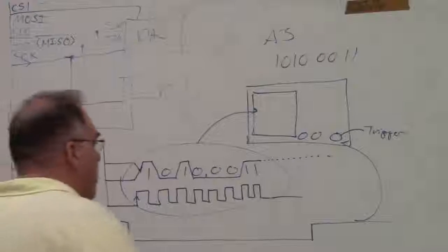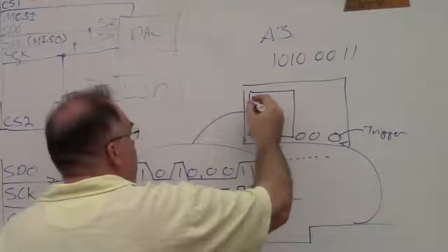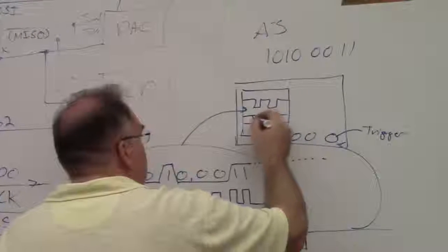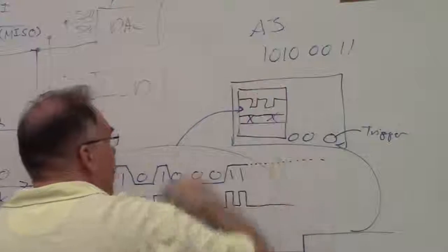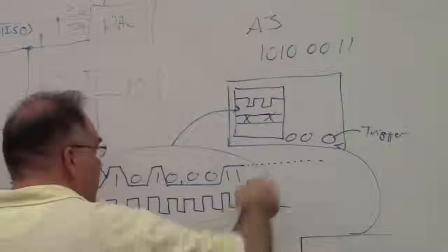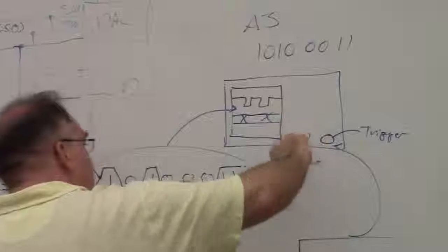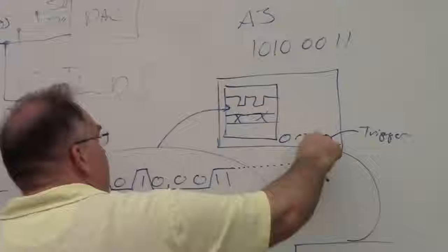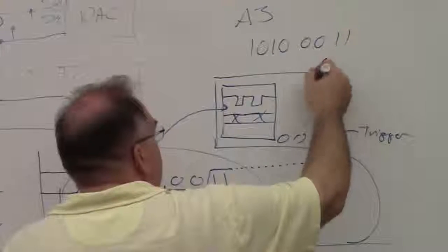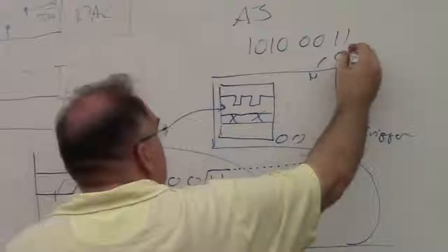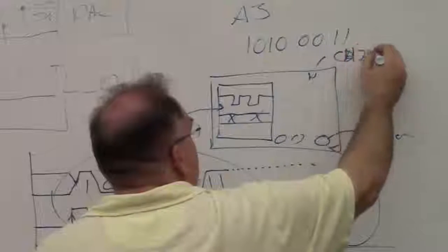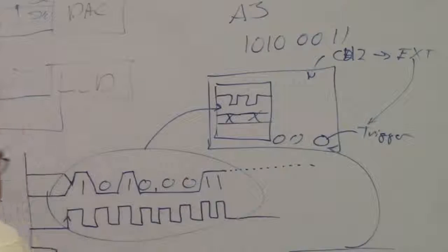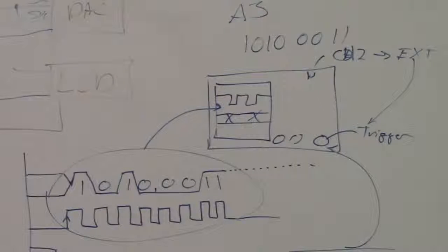What you can do, though, is get these signals up there, and maybe you have some syncing issues. They're on the screen, and you can see some transitions, but they're not quite synced up right. You could take one of these signals off, put the chip select over here, make sure you have a good chip select, and then move it back, and then change your trigger from channel 2 to the external, EXT. When it's on EXT, it uses that third input. All right.